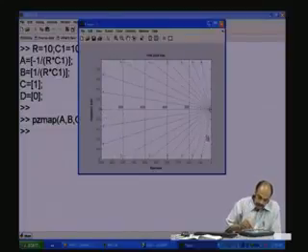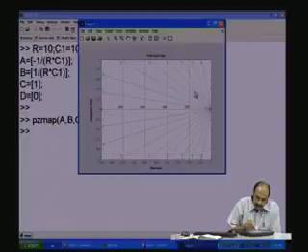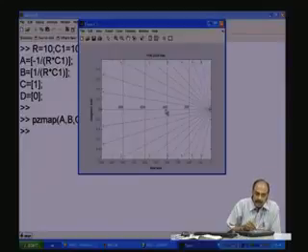Now, this contains a lot of vertical and horizontal lines and also radial lines. What it basically means is that if there are complex poles, these radial lines indicate the damping. If it is on the real axis, it is well damped, over damped in fact, and if it is on these radial lines, there will be some oscillation before it gets damped.